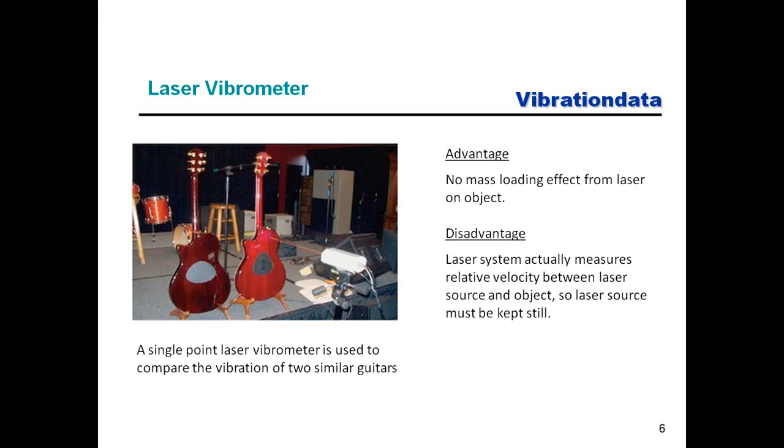effect of the photons. The photons do not have mass, but they do have momentum. That's something that physicists understand, but maybe as engineers we have a tough time understanding that. But let's say that the photon momentum is negligible in terms of influencing the object. Whereas if we took an accelerometer and mounted it to that guitar via wax or glue or whatever, then that would have a mass loading effect on the object.